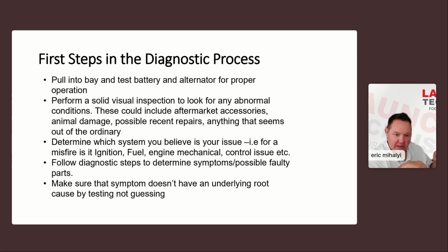Those little plastic clips that go over studs broke. So rather than properly route it with some wire ties or something, they just kind of let it dangle, and now the wiring harness was pulled, a pin came out, and it gave inconsistent contact with a certain sensor or something. Look around. Your eyes are your best tools.